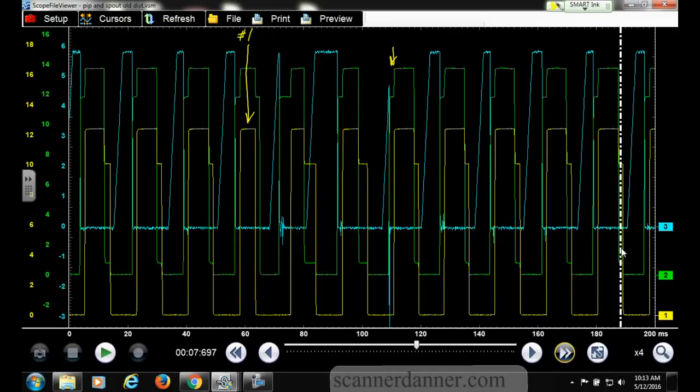It's 1-5-4-2-6-3-7-8. 1542. Yep. 6378. 1542, 6378. Yep. So which one's this? If this skinny one, here's a different version of what we're looking at on that distributor. 4. On this distributor, and then it repeats itself again.